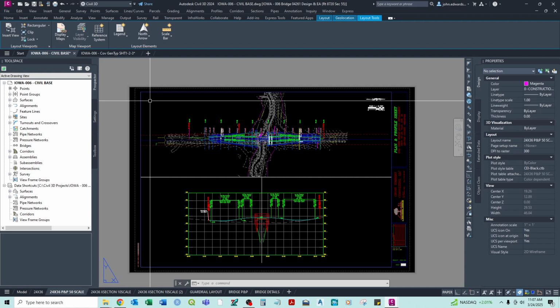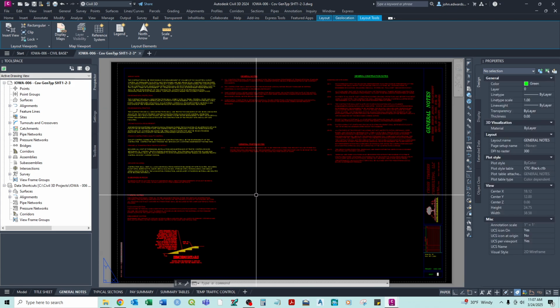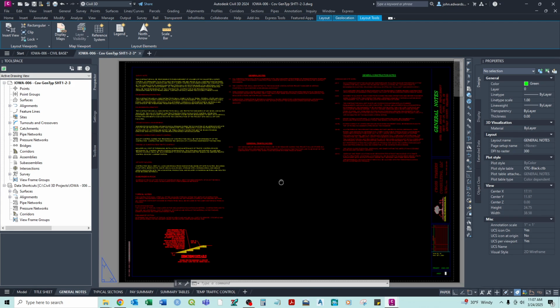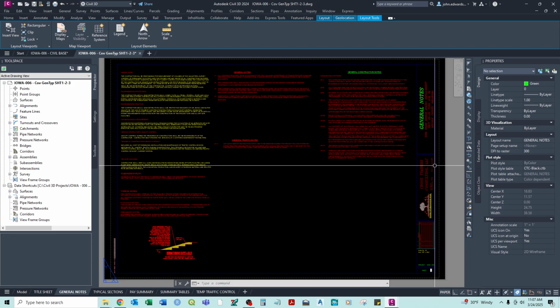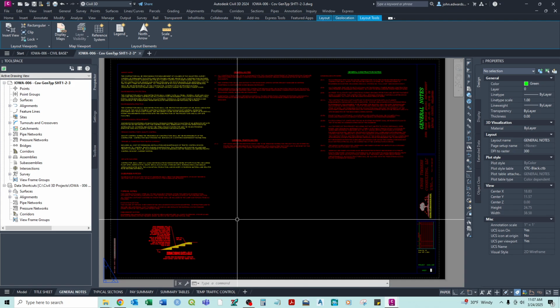And then it's generally easier to not have everything stuffed in one drawing. Once you start getting more than about 8 to 10 layouts within a single drawing, it gets really bulky and can cause issues. You can get to a point where it just won't work very well. The drawing's too big. So it's nice to have separate drawings that have these different layouts. Now it works the same. We have our XREF title block. We have our names and information on these sheets.